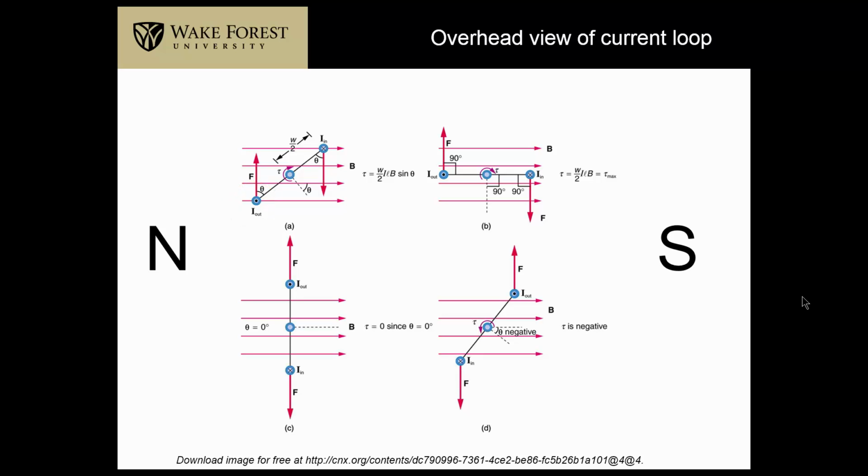The force, which was away from us before, is now toward the top of the drawing on that wire. Similarly, for the other wire, the current's going away from us, denoted by the crosshatch, and the force is downward. It's easy to see then that the torque is clockwise. And you can see a little more clearly here the angle theta that we referred to in the previous drawing.